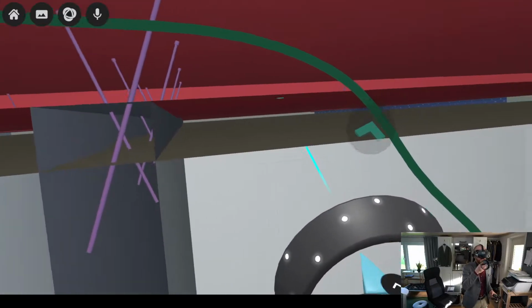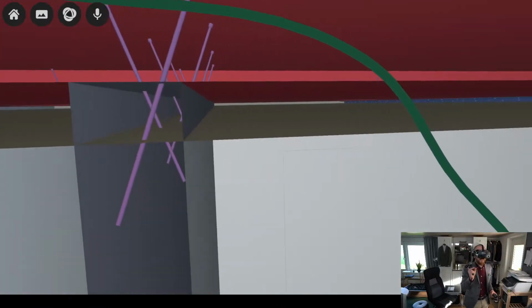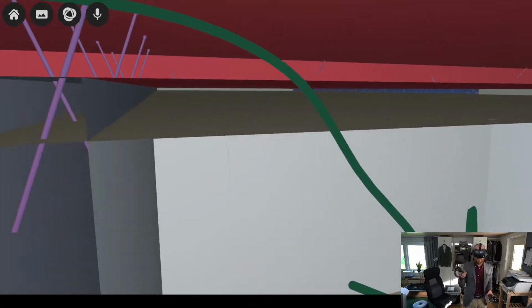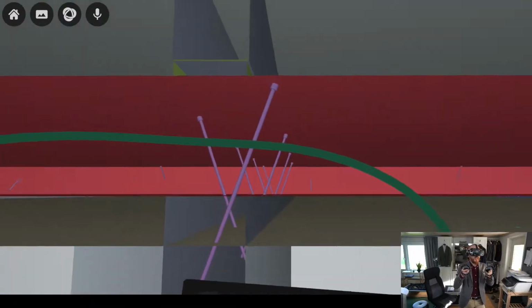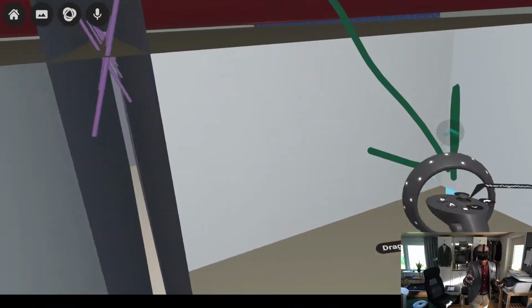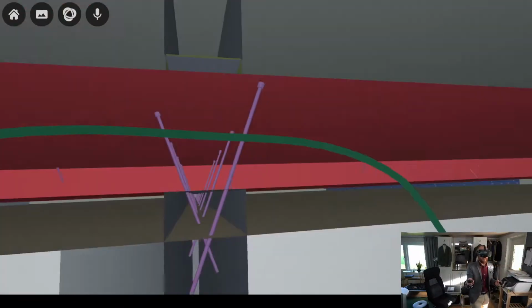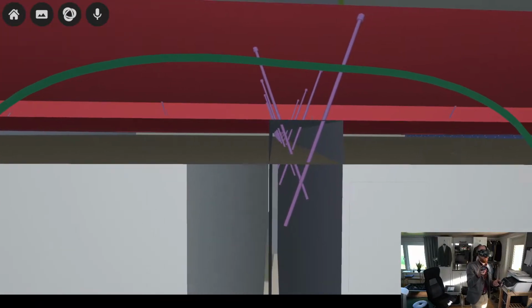I think it's like 22 millimeters of wood, and on those you mount acoustic steel profiles. So this is a suspended ceiling that is somewhat hanging freely, and that way you can significantly reduce this transmission path even when the CLT element is continuous.